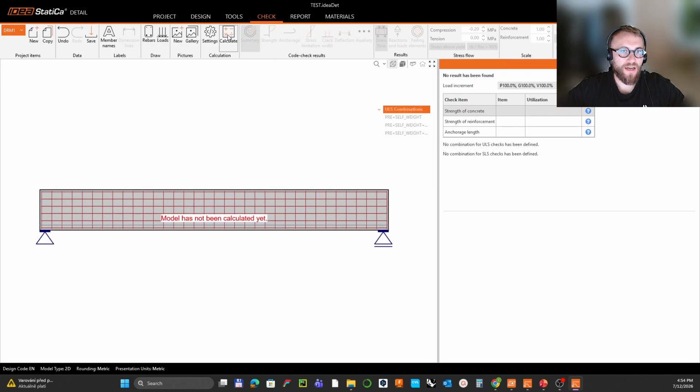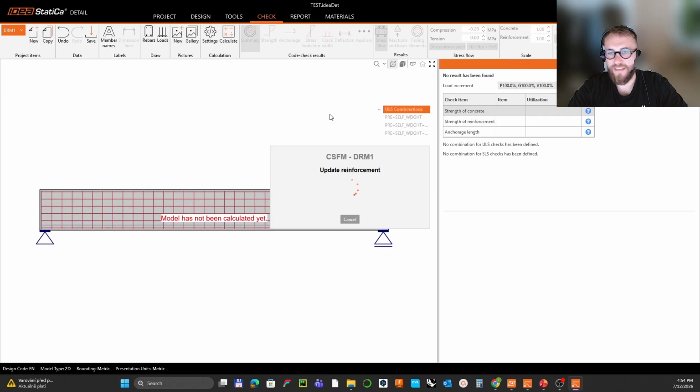There is the nonlinear analysis coming. Materially nonlinear analysis, where for this simulation we are utilizing the parabolic rectangular diagram for concrete with the effect of compression softening, and reinforcement rebars with tangent stiffening on the bars, thanks to the portion and contribution of the average stress in the tension.